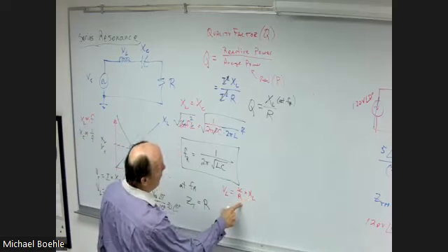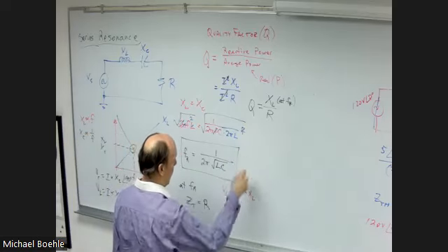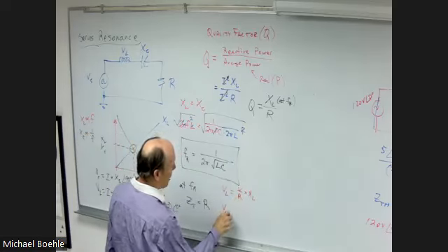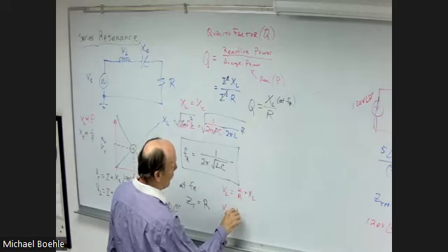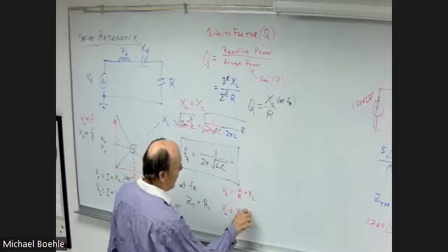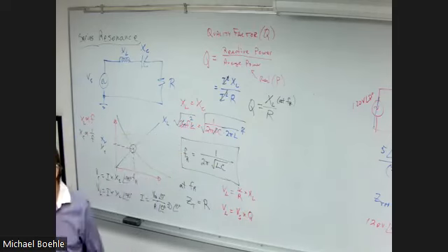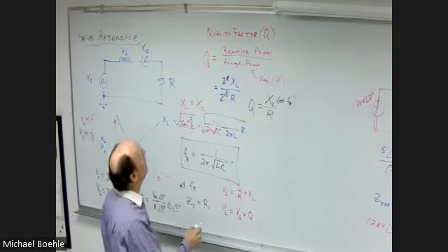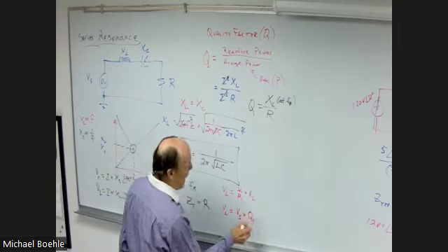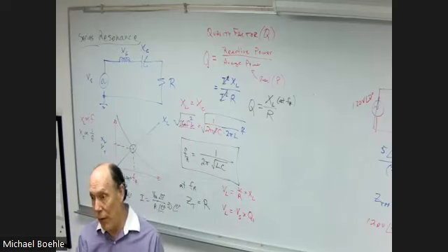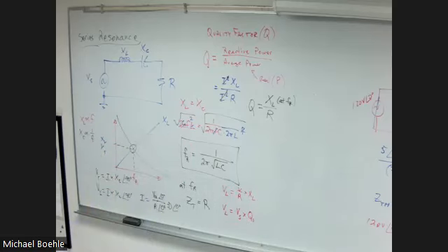Well, inductive reactance divided by R is Q. So the voltage across the inductor actually ends up being the supply voltage times the Q of the circuit. And he puts a Q_S for the Q of the series circuit, because again, the parallel is just going to be all different. So sometimes I put the subscript, sometimes I don't. I apologize if I don't, but it works either way.